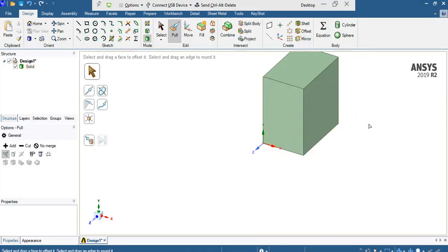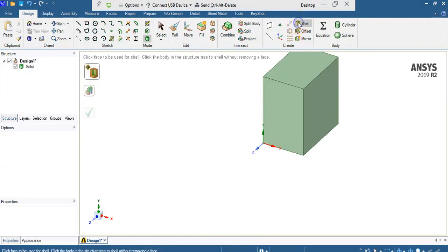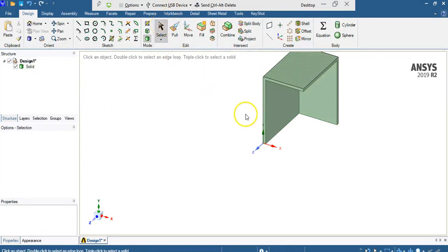initial structure. Now since 3 of the sides are removed from our geometry here, let's do a shell command, and let's select this thing in here. Okay, and it's already given by default of 1.25 inches. That is the thickness of the plate that we are getting here, so you can modify that thing as well. But since in our problem we already have 1/8, so that is fine for our case. Now next we have to,